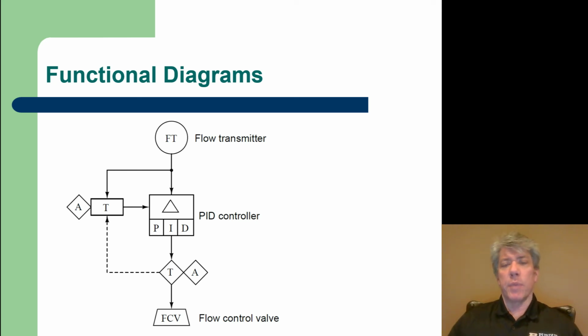Well, remember, the purpose of this PID controller is to control flow rate, right? Well, if the set point is equal to the process variable and error is always the difference between the two, then there's always going to be zero error. In other words, the PID controller will not try to manipulate the output variable, right? The control variable will not be changed. In other words, the controller will be in manual mode. And so we can either choose to have the information, the analog signal of flow rate, go in as the set point for the PID controller, or it can come from another source.